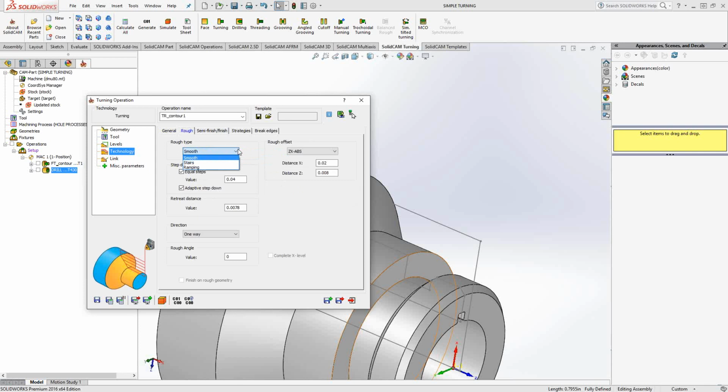As soon as I click on, let's say, going from smooth, you see in the bottom left corner, smooth just basically follows the exact contour. If I change it to stairs, you'll see that it actually will step along that equal step that I've defined down here. So I'm just going to leave it as smooth. Here's the steps of our roughing path.